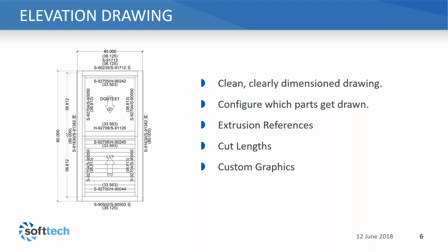The dimensioning also was designed to cater to both what I call frame-based dimensioning for a product like this, where you might want to dimension both the frame and the nested frames, and also what I consider to be light-based dimensioning, which for instance would be where you're effectively dimensioning lights to show the center of a mullion, for example. This could also be expanded to do things like DLO dimensions.